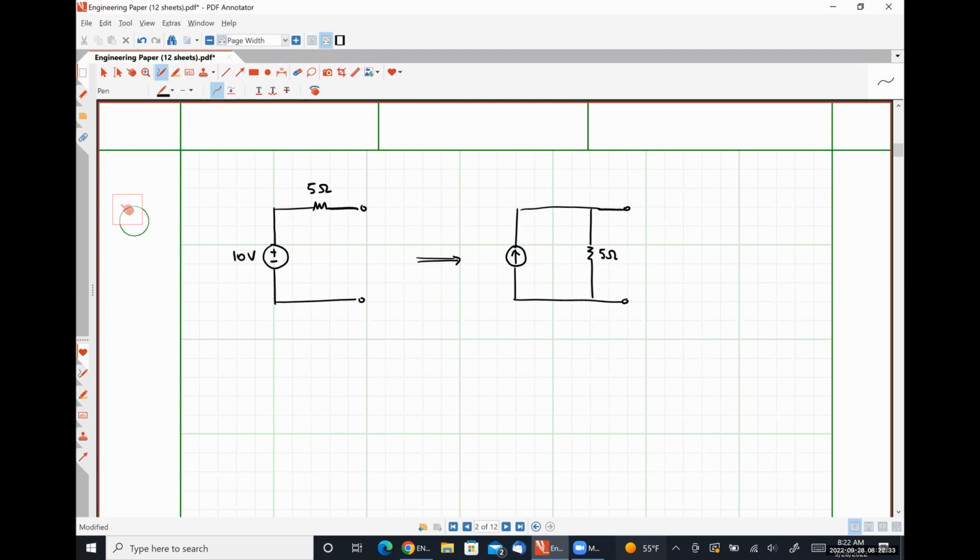2 amps, right? Because this is governed by the relationship that VS is equal to IS times RS, or we could say simply that IS is equal to VS over RS, or we could say that RS is VS over IS. We're not actually going to use this one today, but it will come up with what we're talking about on Friday.